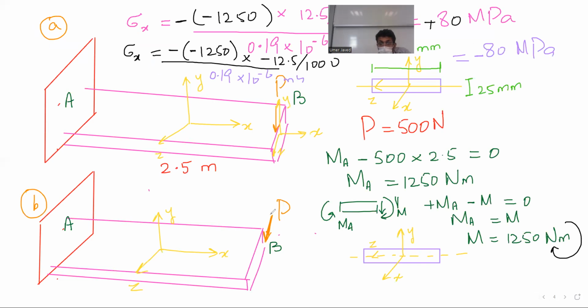Look, in which direction is your force acting? It is acting in this direction, so the beam will be bending like this, right? So this means you will have a clockwise moment around Y. You see the arrow in this direction, so it is negative My.